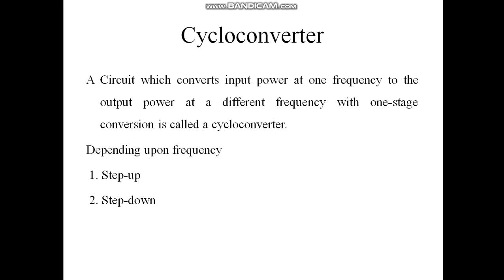A cycloconverter is a circuit which converts input power at one frequency to output power at a different frequency with one stage conversion. It is an AC to AC converter. If it is increasing the frequency at the output side, then it is called a step up cycloconverter. If the frequency is decreasing, then it is called a step down cycloconverter.